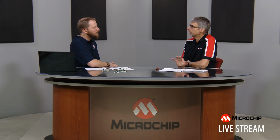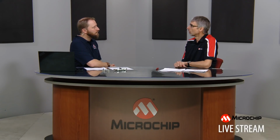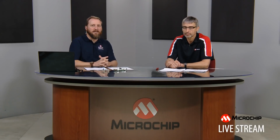Now, keep in mind, lower noise usually comes at the expense of higher supply current. So if you're opting for a lower noise amplifier, you'll probably find that those amplifiers require higher power to begin with. But that's true for any amplifier, whether it be linear or zero drift. Right. Okay. Thank you, Stefan.